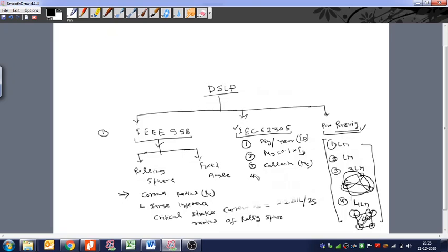Thereafter we identify all types of losses and we calculate the overall probable risk value R, and this overall probable risk value R we compare with the RT. RT is the acceptable risk value. If R exceeds RT, in that case the lightning protection system is required. If less, then it is not required.